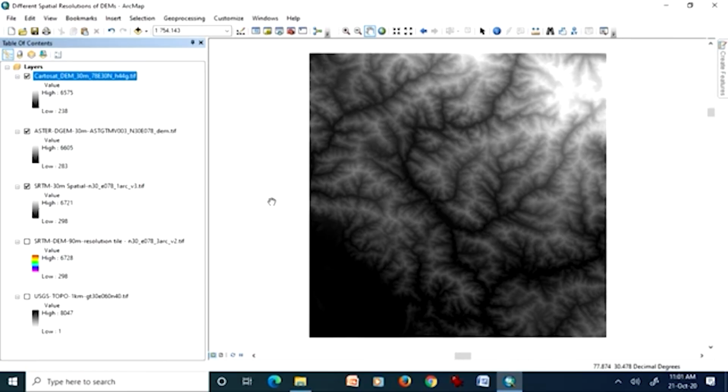If you are using your own generated digital elevation model, then the scenario is different. You can check it with 10% randomly selected points kept in a separate file, and once you have found which interpolation is the best, you can employ all 100% of the points. But here you need some control points to check. If they are not available, then relative checking can also be done using random points. So there are various ways.